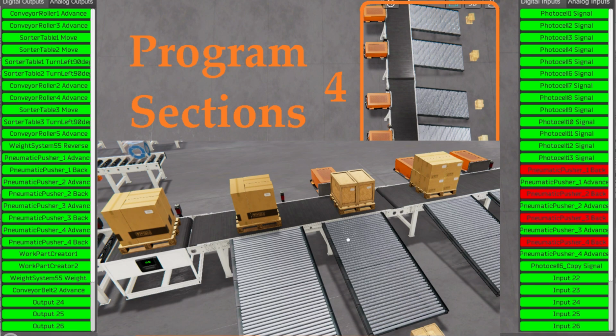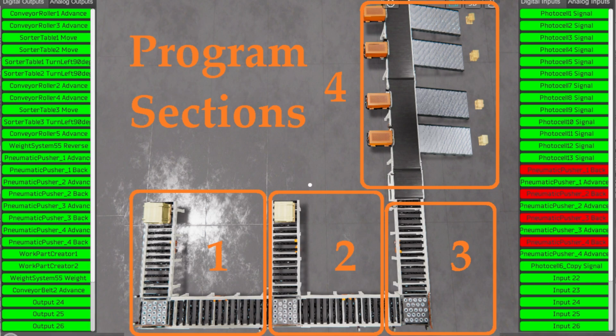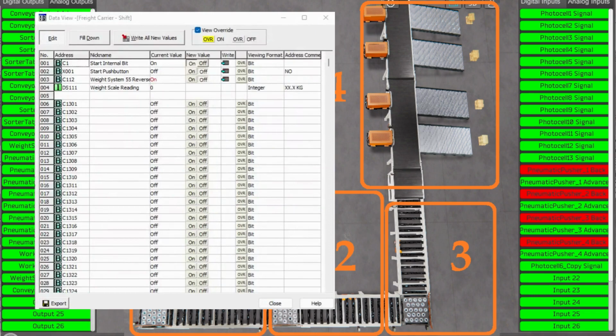Depending on the weight read, a shift register is enabled for the exit ramp. Our example will have 3 shift registers to track the first 3 exit ramps. The last ramp will be the smallest weight and will reject everything that is detected in front of it. Normally a shift register will track parts by a mechanical gear on the conveyor belt, but in our case we'll be using a pulse time bit of 500 milliseconds. The sensor beside each of the reject cylinders will ensure that our timing for the reject is accurate.